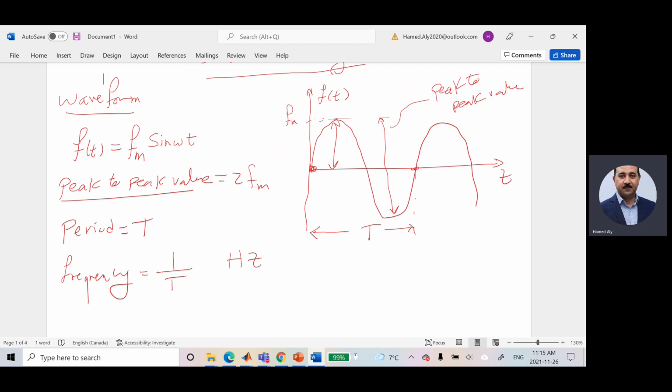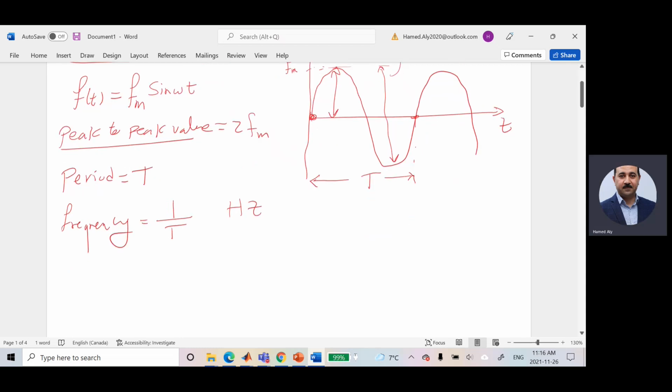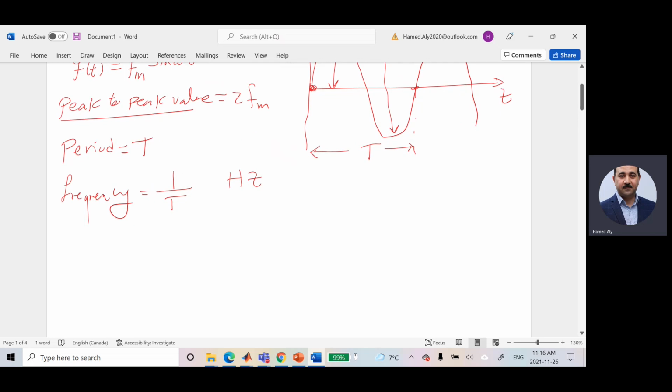Yes, because we would like to find a specific characteristic that will represent a constant value of the voltage. Those who are dealing with that try to reach a specific value that will represent the characteristic of that voltage instead of measuring different values. And this value is constant, but I'm using AC. The value that I'm measuring is constant at any time. What is that value? They are calling it root mean square. So we have two different things. Number one, mean or average value.